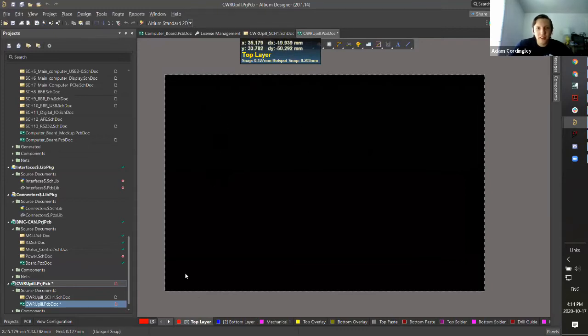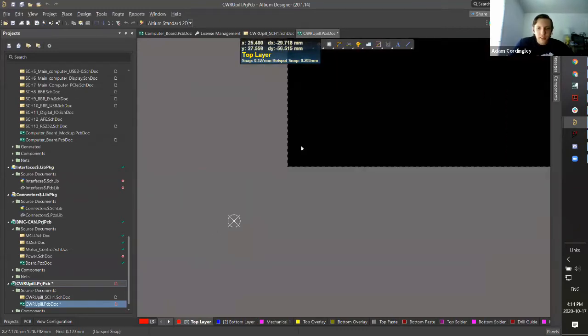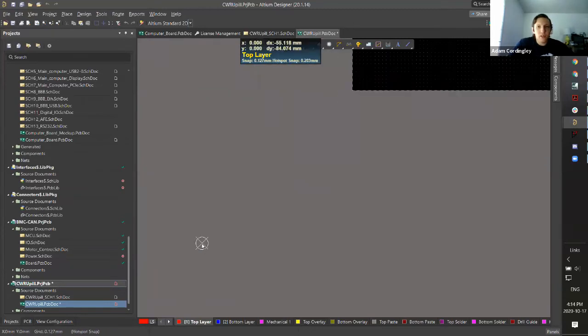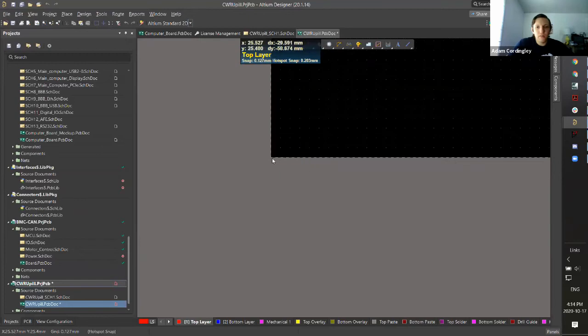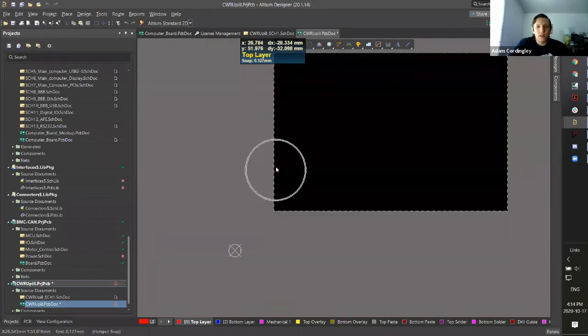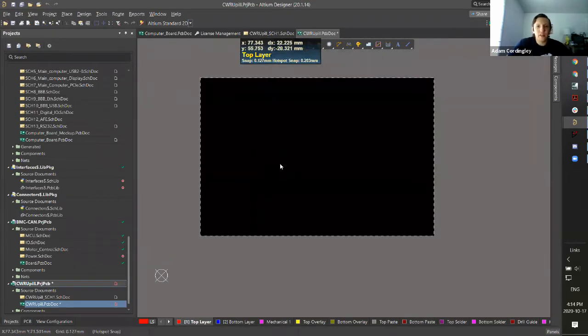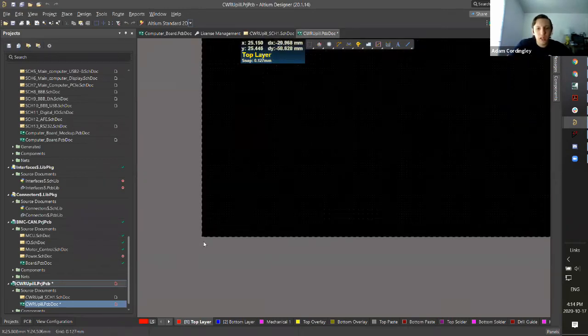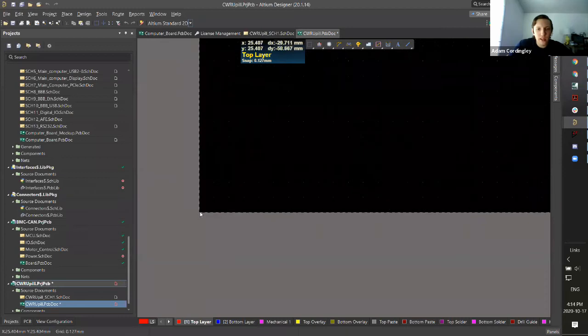And everything's in millimeters. Great. The next thing I want to do, you don't have to do this, but I like to change the position of my origin to be the position of the origin on the board. We'll resize the board later. It's just giving us some random size pretty much. But I like to put the origin right there at the corner of the board.